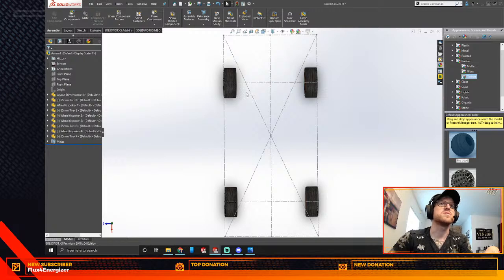Let's say we'll have suspension arm coming out here, one coming out here. How far they're going to be, not quite sure. It's not going to be too long. Same thing up front. We need to have enough space to have steering linkages. So let's say we're going to make the arms connect around this point.